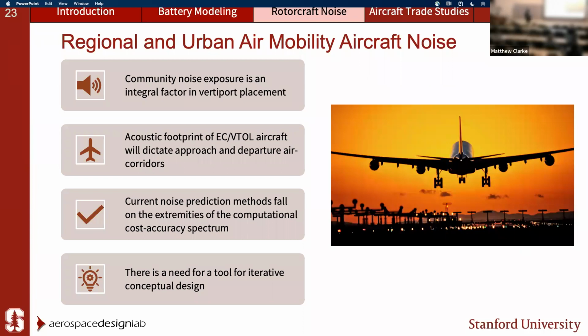Yeah, so the battery, I kind of glossed over it, but the battery models actually consider not only the energy used, but things such as the C rate and temperature, right? Those cause the degradation of the cell. Those cause certain other nonlinearities in terms of the discharge profiles. So those are taken into consideration in these models as well.